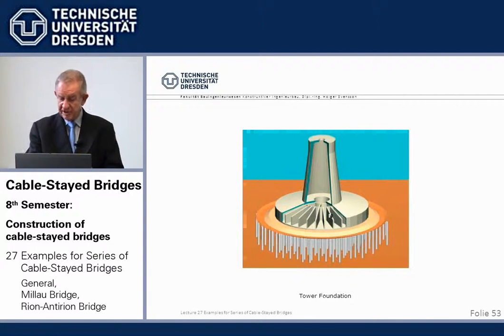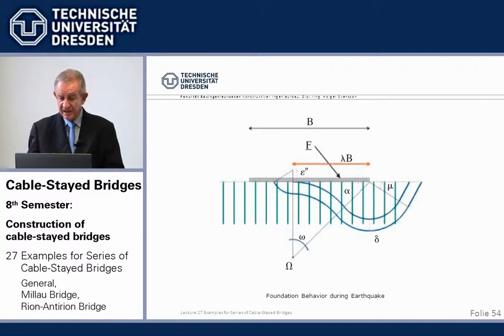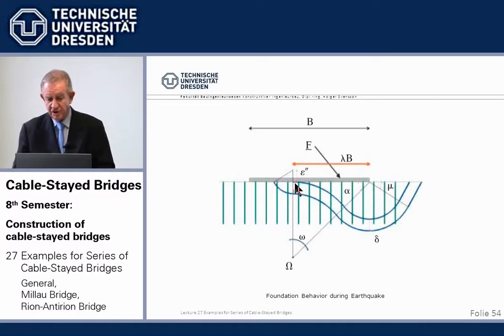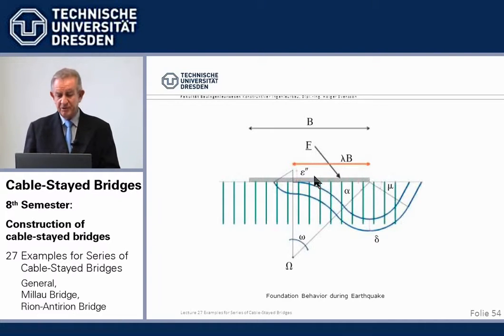We know already about the movement there, and this is some way to show in soil mechanics we prevent the shear failure in this deep plane, Grundbruch. We avoid it by ascertaining that this slides before the shear failure here takes place. Quite an involved geotech investigation.